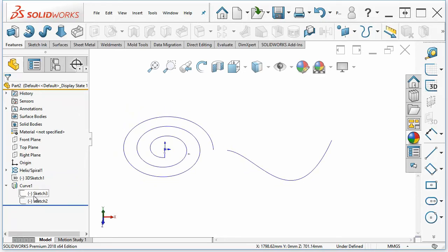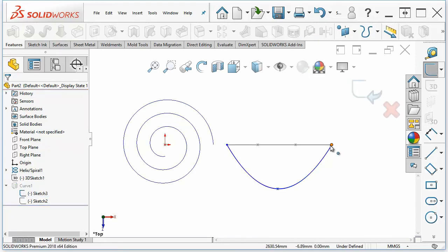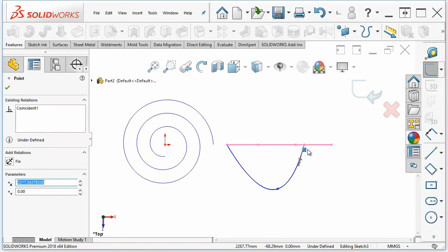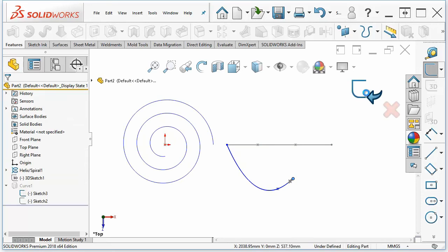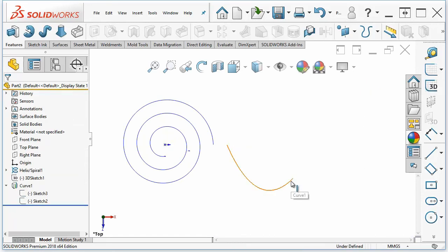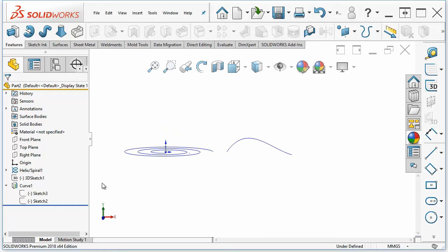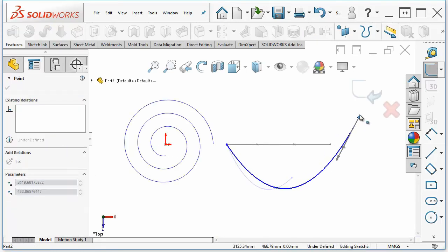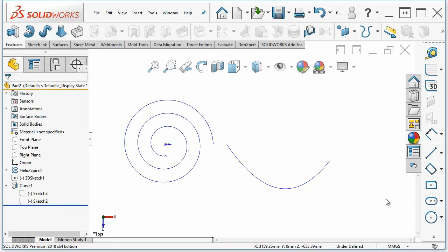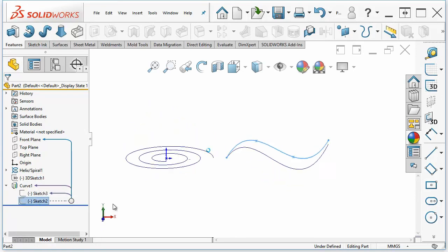So it matters which one is shorter. If I pull this one back, I delete that relationship there, I can pull this back like this, and that way my curve only goes that far, and it's not going to represent the entire sine wave. Okay, so it's really just going to do the shorter of the two curves. I could make this one extra long, and it will still only do the shorter of the two curves, which in this case is the sine wave.